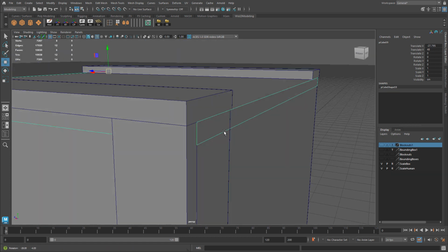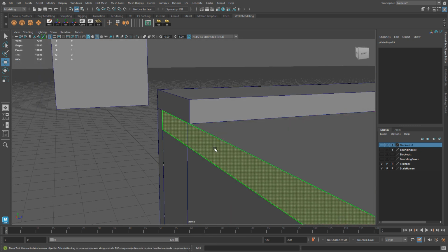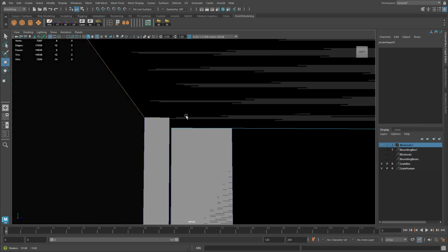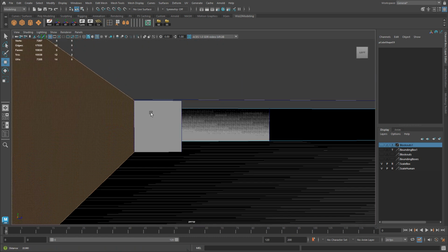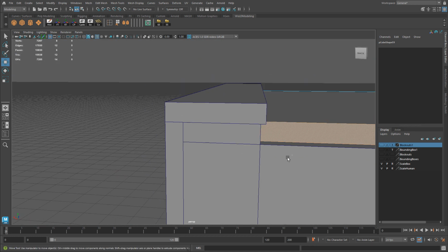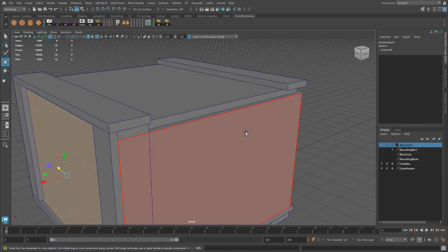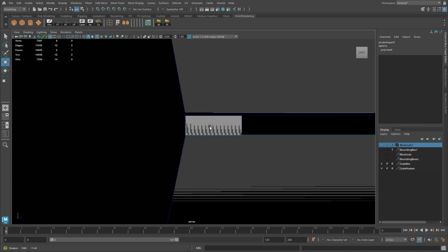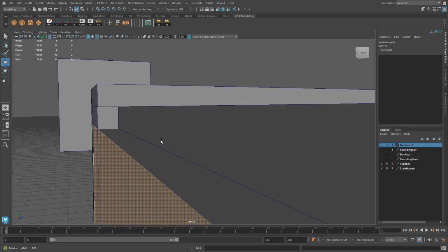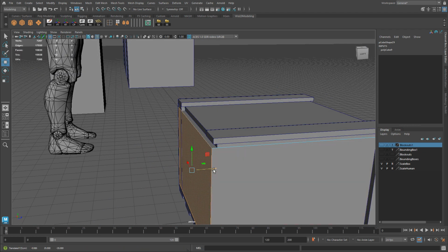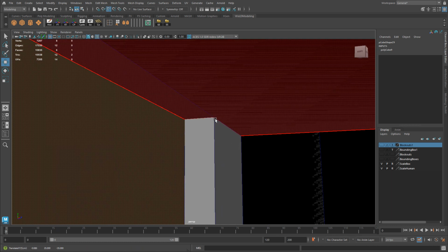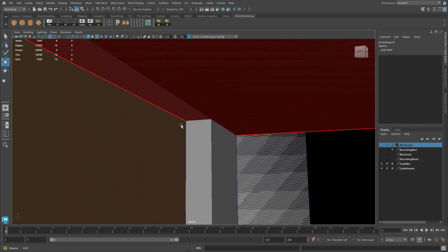Now that I have these positioned, we just have to snap these faces. I'm going to highlight the Z-axis, and I just need to find that vertex to snap to, which is going to be this one right here. Hold V, middle mouse click and drag. Done. And let's do the same thing for this face. What we need to snap to should be that vertex right at the top. Hold V. Actually, I want to make sure that I highlighted the Z-axis, and I did. And let's snap. Once you try this a few times, your ability to snap will speed up by a lot.